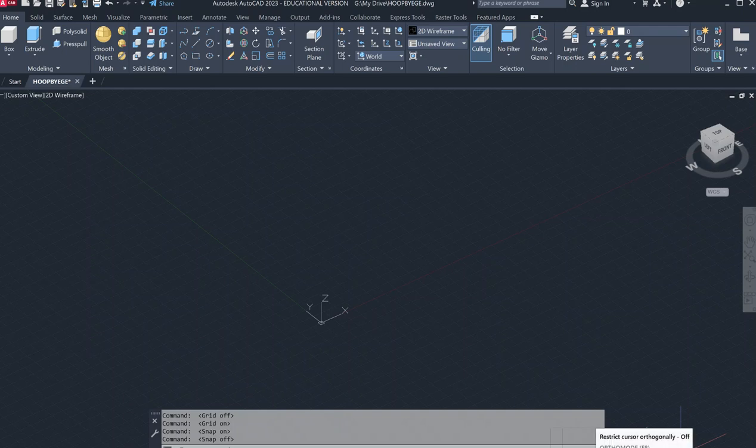Occasionally, you're going to need perfect ortho mode, perfectly vertical lines to surfaces or the XY plane. So you need to turn the ortho on when you need it. Right now, it is off, so please don't use it now. There's object snap tracking. That's a very good quality of your cursor to enable you to see and mark endpoints of other lines nearby or intersection points of other lines nearby. It shows you when you click on it and make it blue, but right now I don't need it, so I'm turning it off.